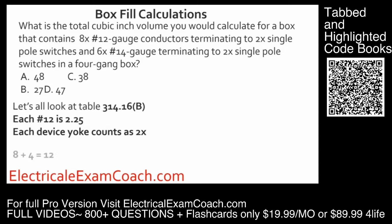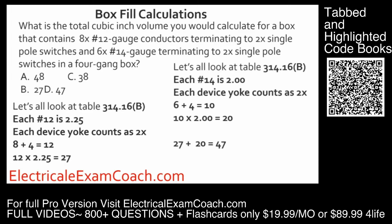Let's go ahead and deal with our 12s. We know that we have 8 conductors and 2 devices for those 12s, so each one of those devices counts as 2 more, giving us a total of 12 12-gauge conductors. We bear the math out, and we end up with 27 cubic inches. Now we just do the same for the leftover devices. We have our 6 original conductors, and we have 4 more based off of our count, because remember, it's based off the largest wire that terminates to that device. We bear that math out, total the two together, and end up with 47 cubic inches. Let's get to it.